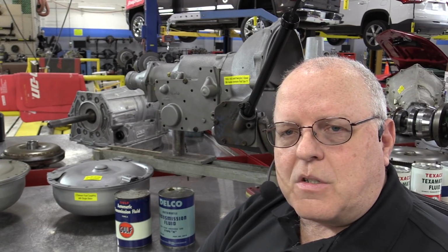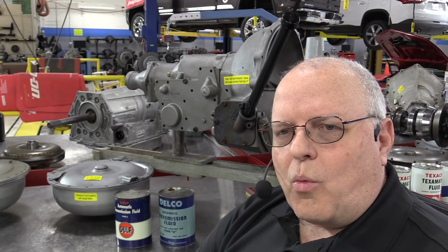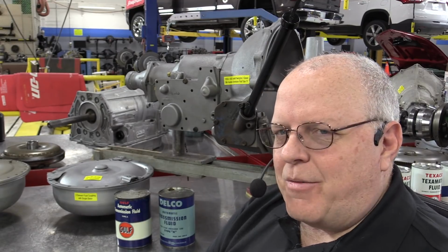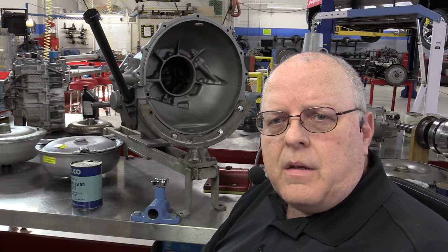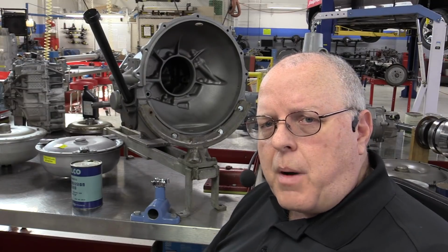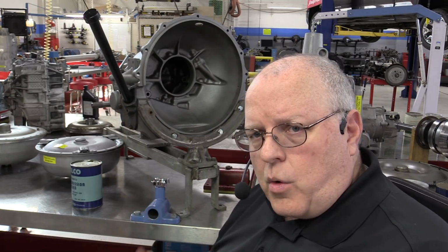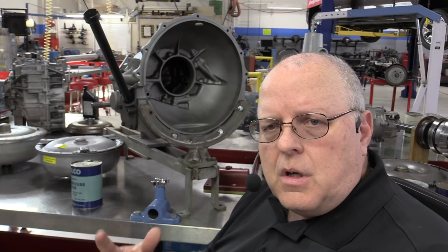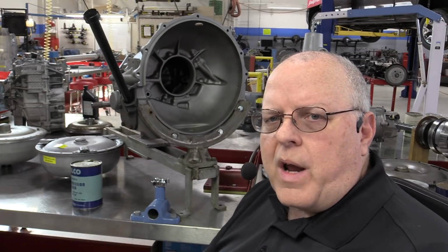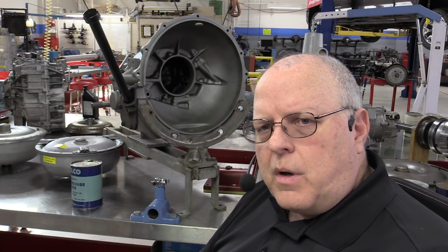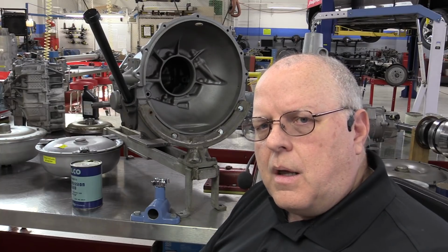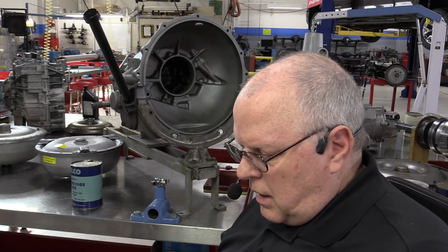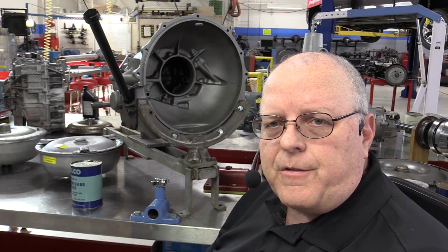But back then, they were designed to do that, to try to rock the vehicle out of being stuck. A little bit of trivia there. By the way, the 1950 and above Chevrolet 2-speed Powerglide transmission with that torque converter caused so much heat and oxidation, which is air mixing in with the fluid and reacting with chemicals in the fluid and materials in the transmission. It caused the need for a revision in the Type A fluid specification. That revision took place in 1951.